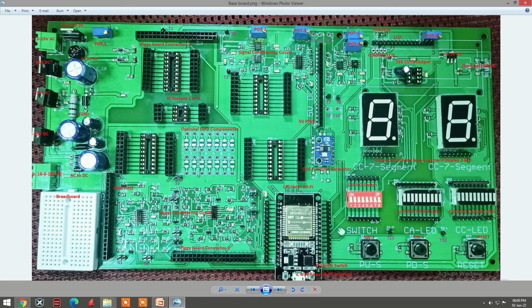Before transferring, you are supposed to press this small button called the boot load button; the software will ask you to press it. So there is a switch here, please remember. If you press this tiny switch, then only is the program loaded into the CPU and will start working. Working in the sense of data acquisition, communication, or programming your function generator.